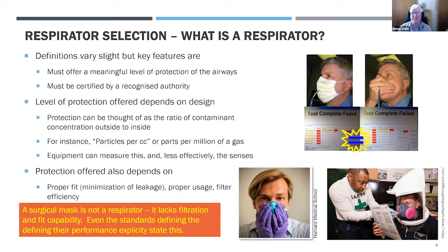And then we have fit test methods that rely also on the senses, the qualitative fit testing versus the quantitative. And again, that's something that will be discussed. Just to mention, a surgical mask, although they are widely used, it's not a respirator. It lacks filtration and fit capability, and those are the two things that are important in respirator performance.